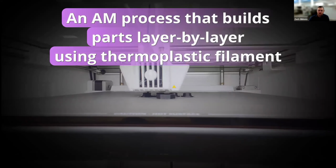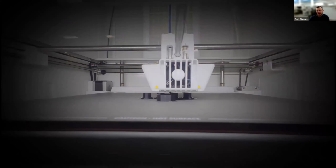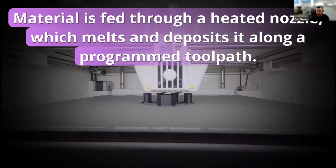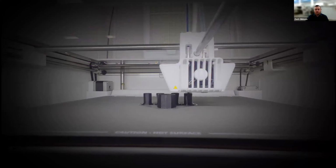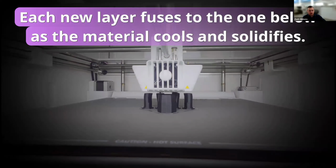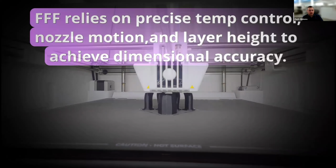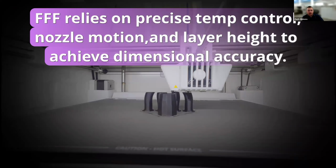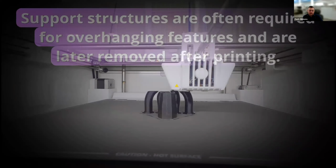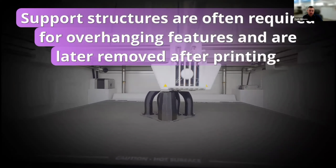We're building parts layer by layer, in this case using thermoplastic filament. We're feeding that material through a heated nozzle. We're melting it. We're depositing it along a pre-programmed toolpath. And as it prints, each new layer is fusing to the material on the preceding layer. Right? So we require precise control of temperature, nozzle motions, and layer heights to achieve that dimensional accuracy.